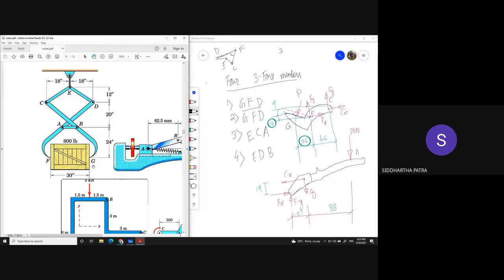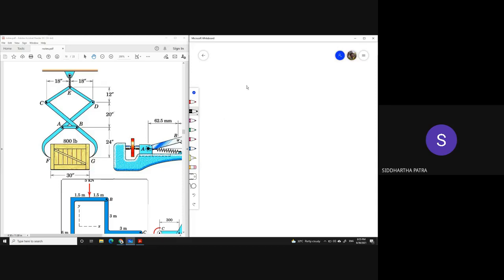But you see, whenever you are trying to grip something and pull it up, you are doing it by means of friction, and friction force cannot exist without a normal force. So of course, in addition to having this tangential force, which would be vertically downward, all I'm saying in this problem is, if I draw the free body diagram of this member right here, which is C, B, and G, and I'm not drawing it very nicely, but you should, and you should provide all the dimensions.